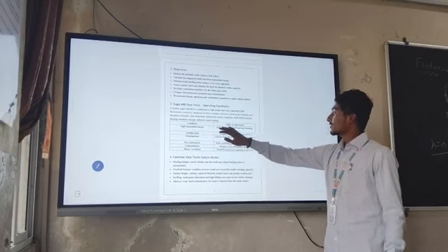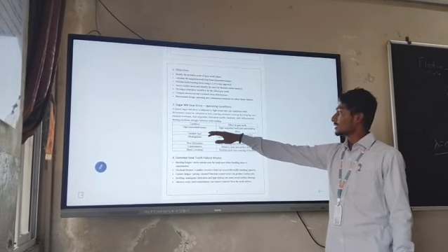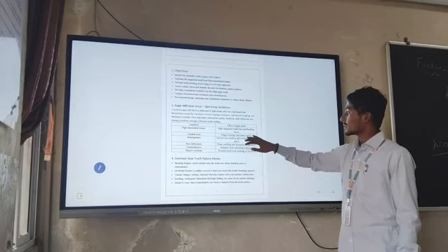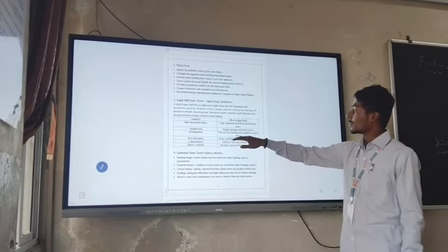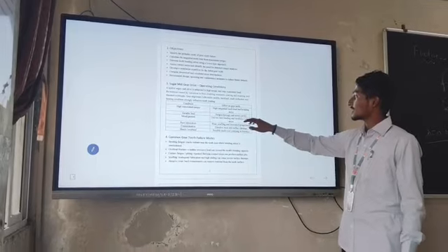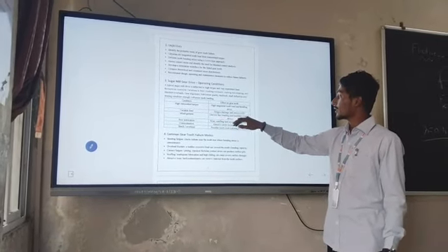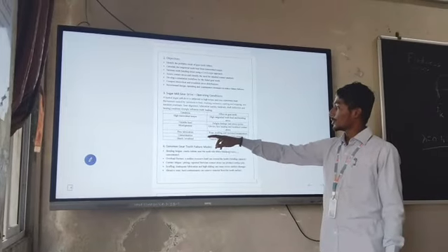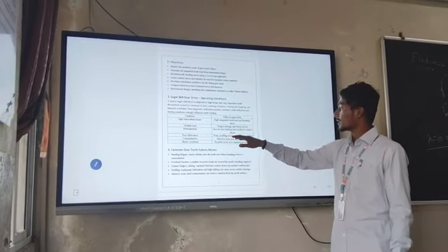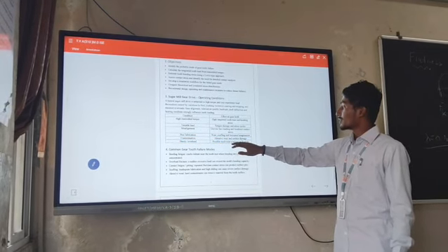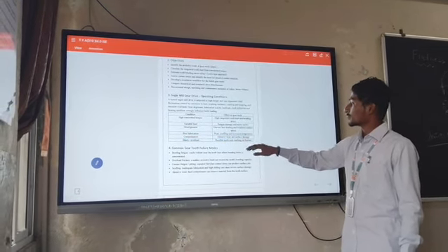Next one is sugar mill drive operating conditions and their effect on the gear tooth. High transmitted torque causes high tangential load and bending stress. Variable load causes fatigue damage and stress cycles. Misalignment causes uneven face loading and localized contact stress. Poor lubrication causes wear, scuffing and increased temperature. Contamination causes abrasive wear and surface damage.